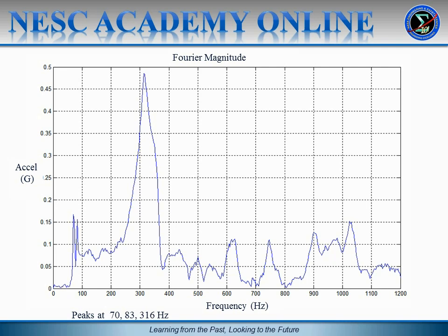For example, if we had some modal test data or some finite element results, then we could compare that with the flight data. Now we need to be a little bit careful about the spectral peak at 316 Hz, and it might represent the combined effect of several modal frequencies which are closely spaced in terms of their respective frequencies.